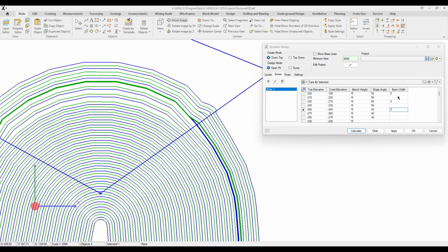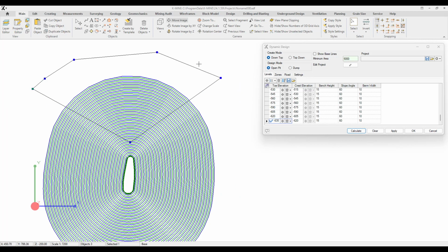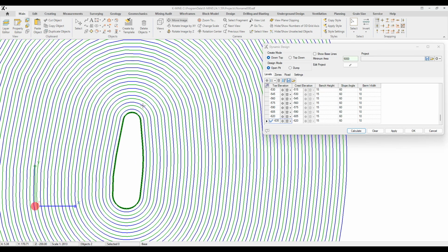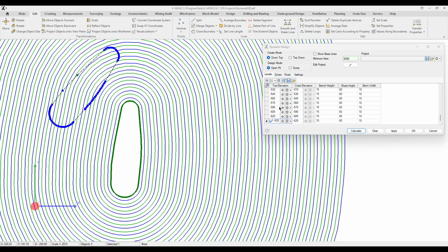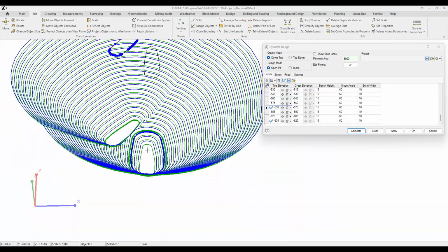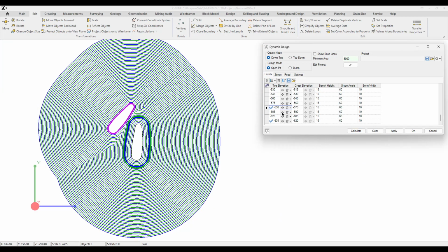Typically, our requirements include having not the one base edge, but several. Also, several pit bottoms, unique configurations of a mining zone at specific levels, and so on. Once we add the boundaries to the right level, they are instantly incorporated into the design. We can also add or delete baselines, either by one or in groups.